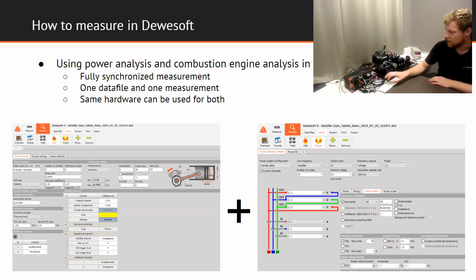In this case, we are also measuring 4 times current. So the current clamps are powered directly from the modules. We need, in this case, 4 times low voltage modules to power the current clamps directly. They have also test chips inside. So as soon as we connect the current clamps, they are detected, all the scaling is set, and we can immediately start measuring.